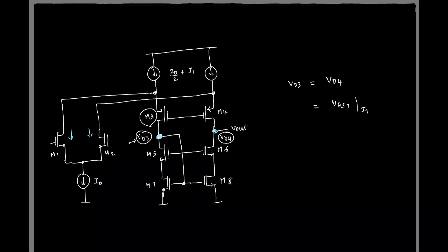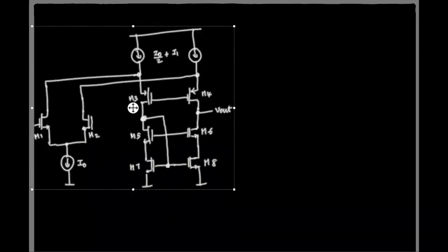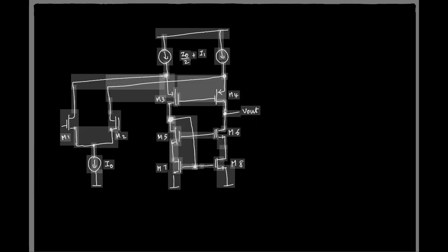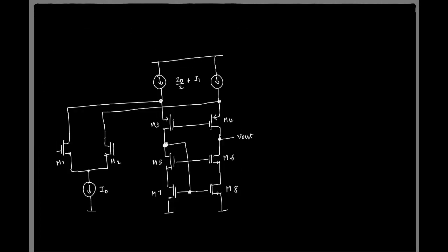Great. Next let's look at the incremental gain. Again, we'll assume that we have inputs V1, V2, and we'll try to find the short circuit GM and the output impedance. For short circuit GM, I'll short this output, and I want to find what Iout is.